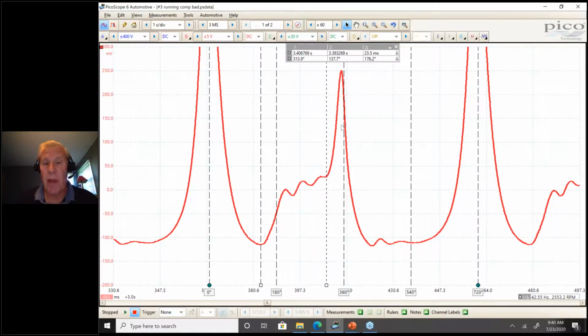you see a significant increase in pressure. I believe that's when the exhaust valve closed. That piston was coming up, the valve closed too soon, and we compressed air in that cylinder. So I could be off a little bit, but I'm not off that much. So my duration is 176 degrees. So before it was reasonably 230. So I have less duration, and I have an EVO that's shifted about 20 degrees.